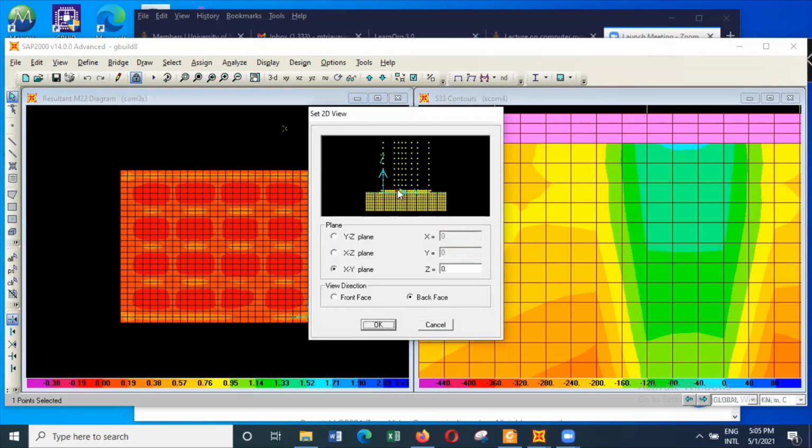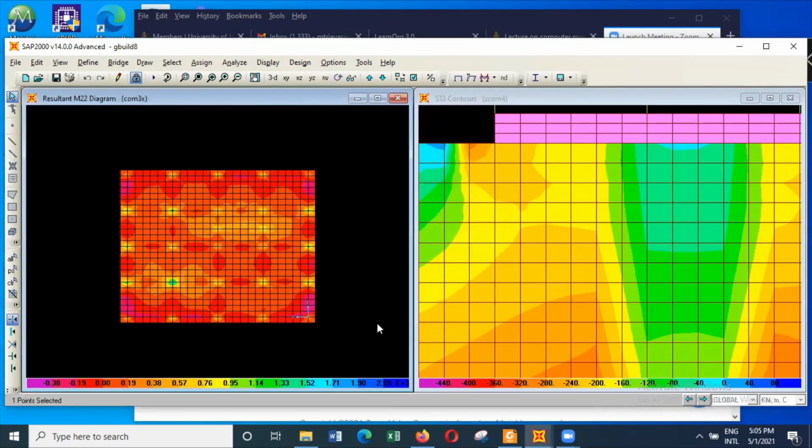and that is Z is equal to 1.5. Most of the locations here you get very low values because it's not subjected to very high loads, except the loads that are coming from above. But there can be some additional moments due to the deformation because we have a weak patch here. And then other locations you get a moment of something like 104.